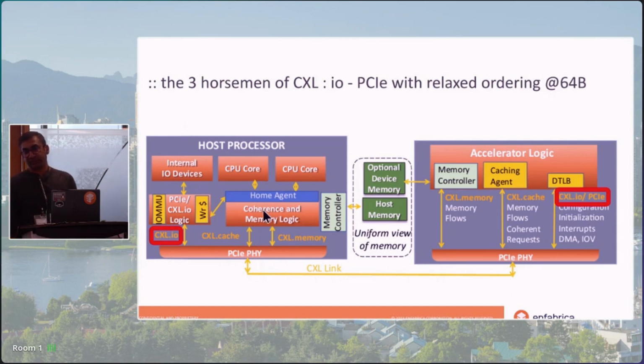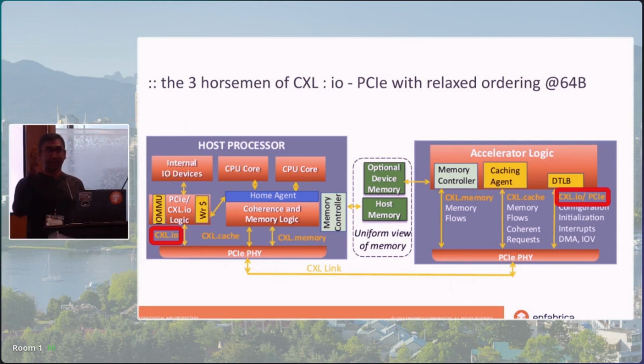And what CXL cache allows you to do is to tap into that and have external accelerator devices that can now be part of that caching domain. Specifically, and to make that very concrete, where a NIC, for example, if I was talking to a CPU, I would have to use DDIO or something like that to push a line of data into your CPU's cache.